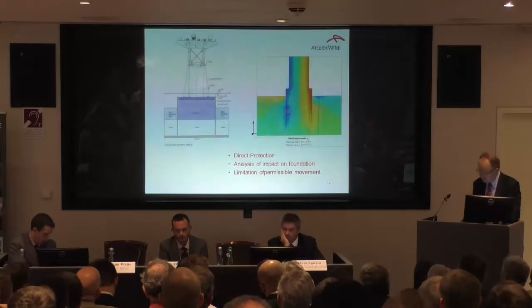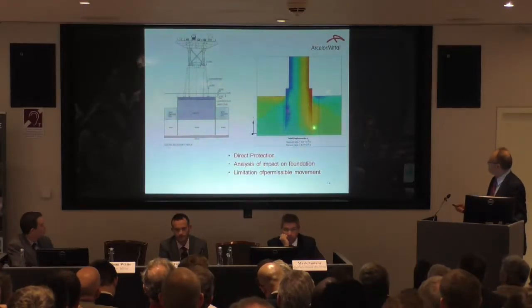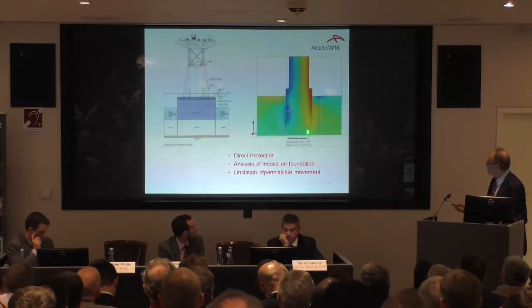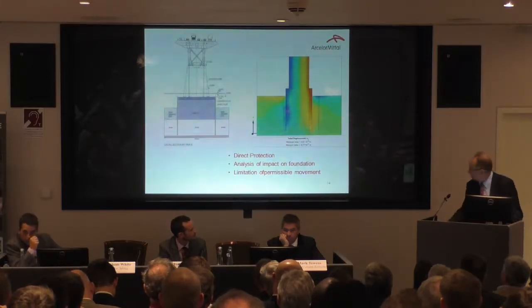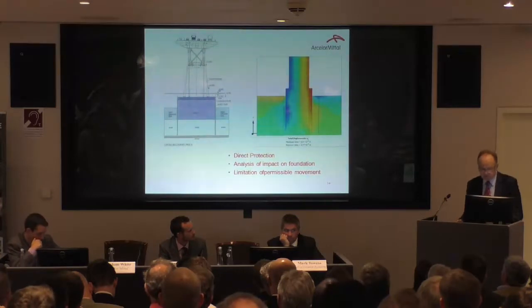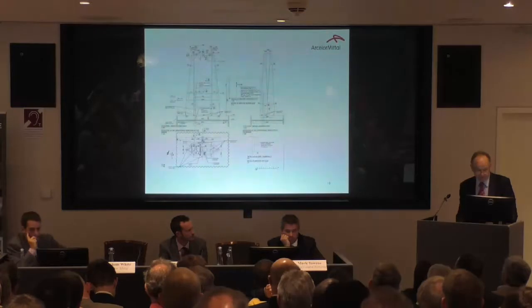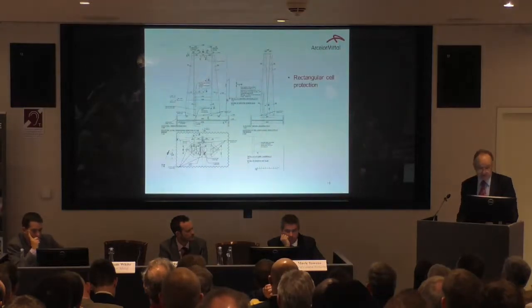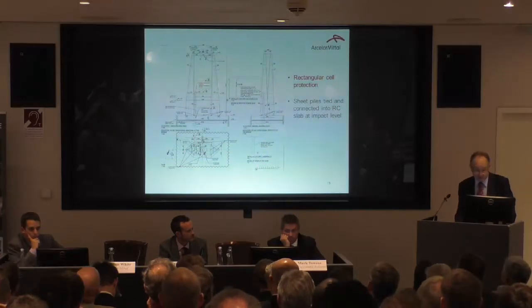In this way, you can actually beef up the stiffness of the embedded retaining walls by using combination wall systems or combined wall systems to get fixity, and then calculate the analysis by rotation from fixity from the very high impact loads. So this is at the top end of the scale, and basically the details will be for robustness at the level of impact.